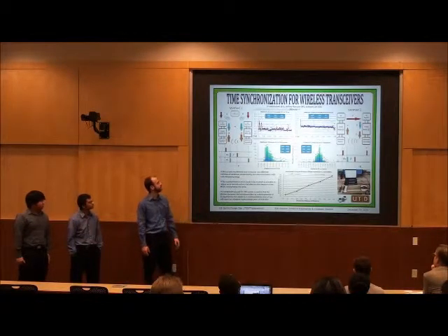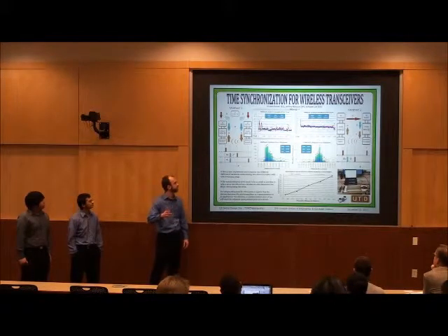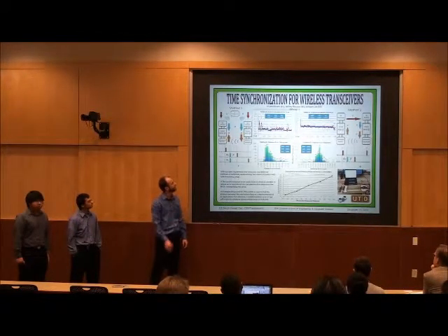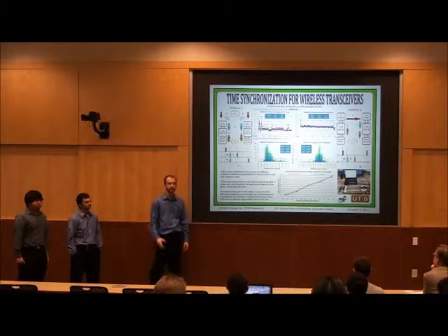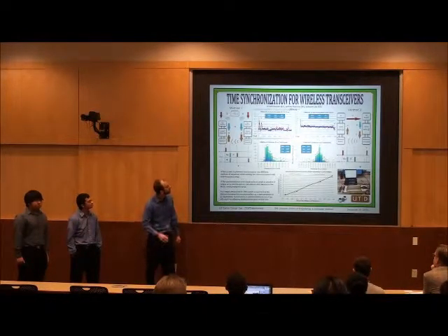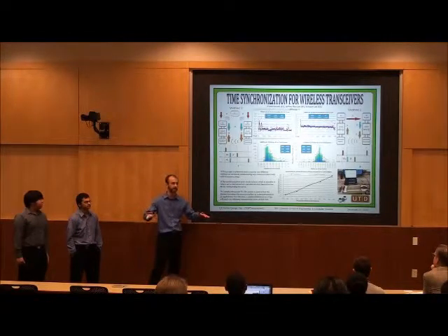And here are our results. The top left graph you see had a variance over 600 trials of about 35 milliseconds, standard deviation of 0.188, and max synchronization error that we measured at 1.106 microseconds. The second one had a max error of 2.455 microseconds with a variance of 0.024. What the variance means is how consistent these data points are, how close they are to the average. And since they have a really small variance, that means that